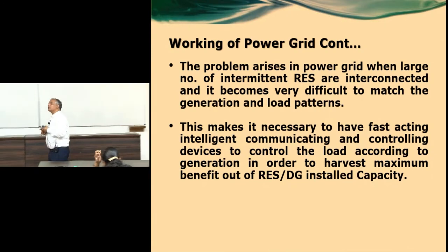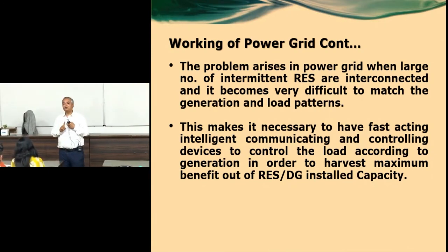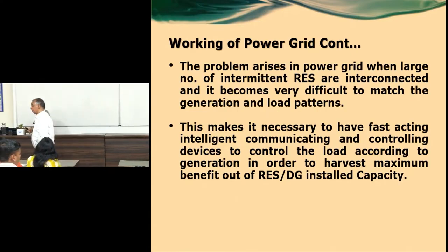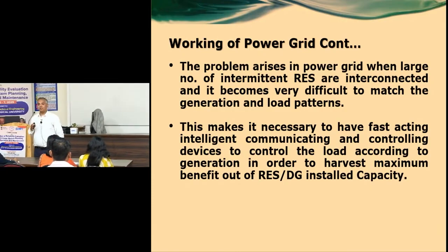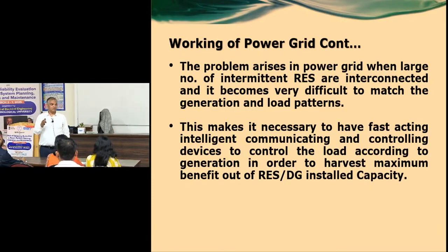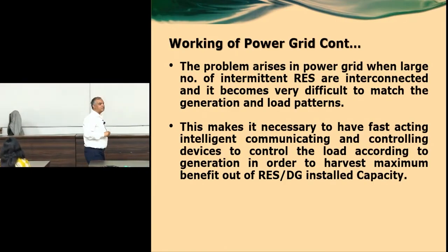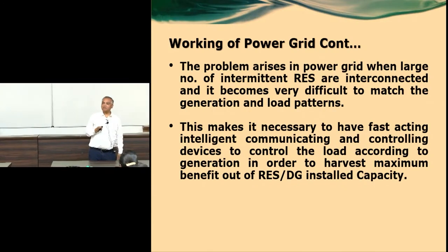So distributed generation is no more a typical distributed generation. It is again becoming conventional generation, where wind turbine and solar power plants of 3 gigawatt, 3000 megawatt capacity are coming up. These act just like typical conventional generating stations, and the power from these locations is transferred to the load centers through the transmission line network only.